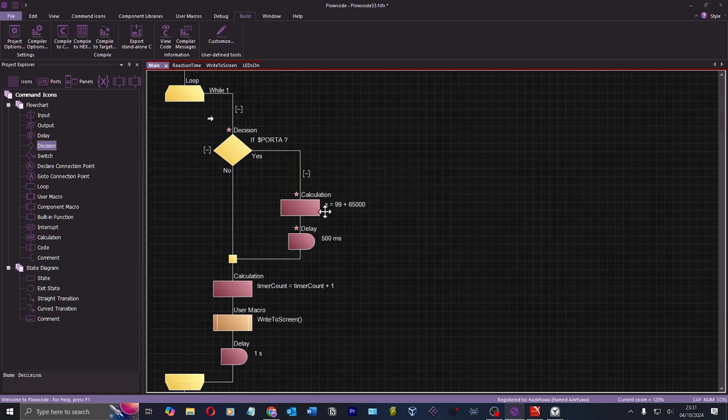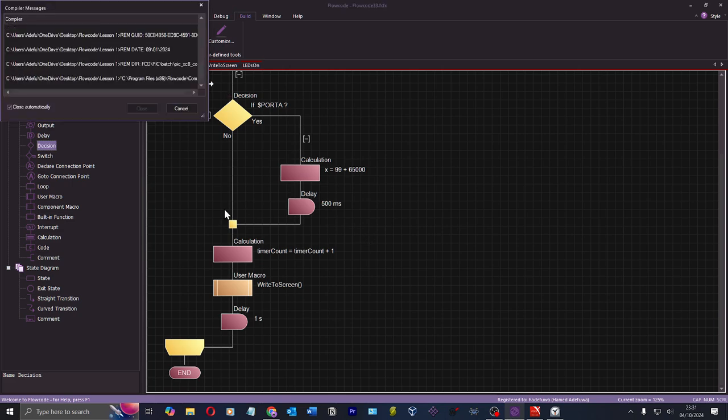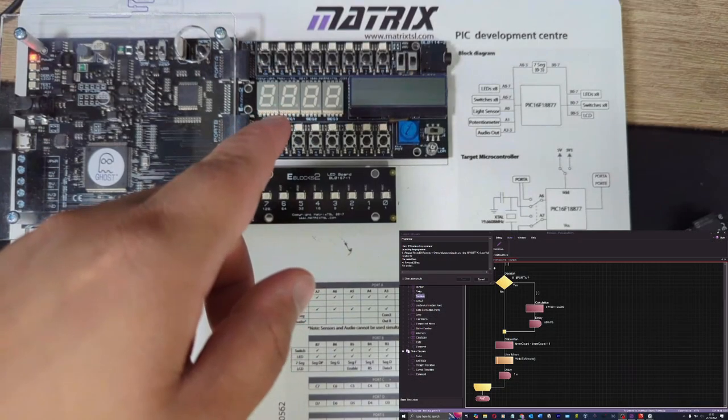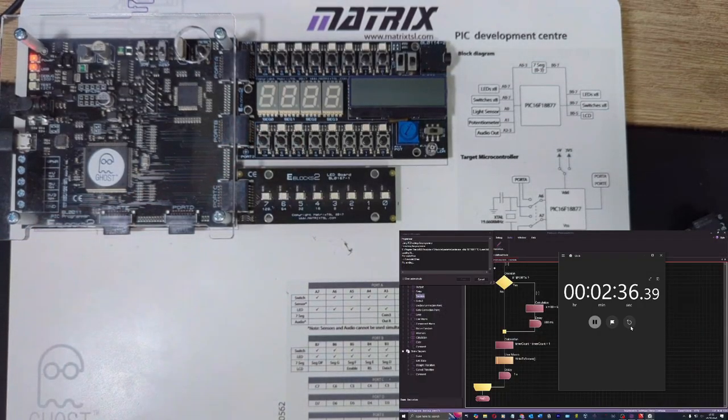So that now is going to start to throw the microcontroller off, and because I've got this 500 millisecond delay, that will then mess up the timing. So I guess by using an interrupt, that won't happen. Even pressing and doing other stuff in the code, it won't mess up.